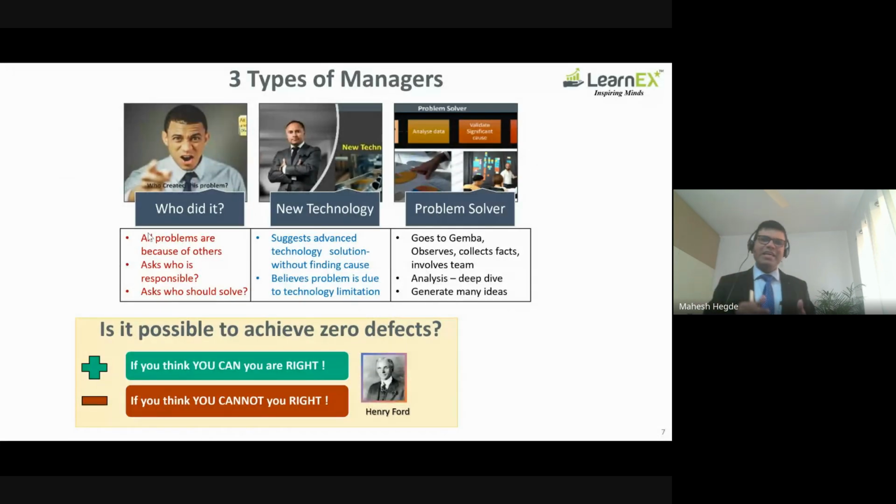Then it was easy to know which test bed is giving good results consistently, and which test bed has variation in results. Analysis, and then they found that in the testing there is some oil, the temperature of which varies in places, so that creates an impact on the results. Then they corrected it and the problem got solved. Just to give you some examples.